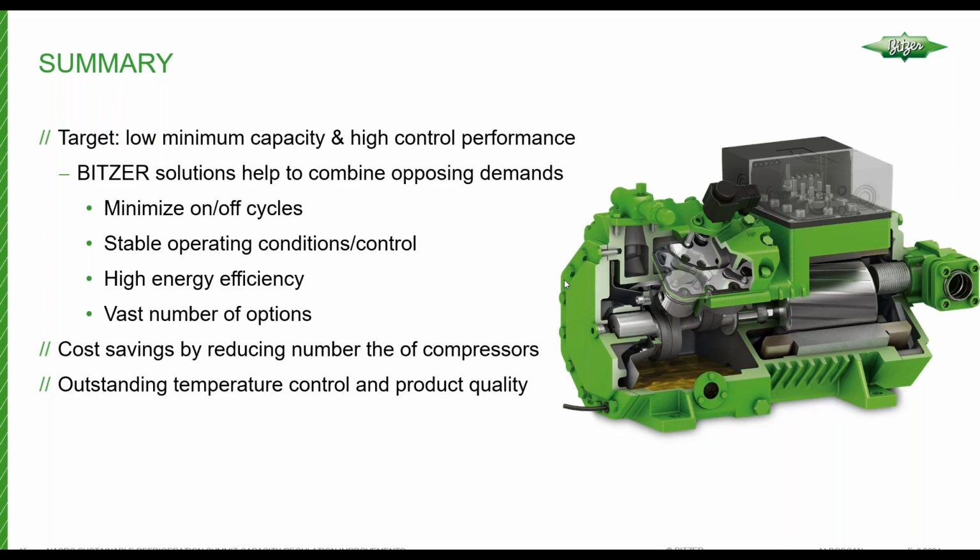It's not to replace the VFD. It can, but the intention is not that. It's to enhance the ability of a rack designer to use more tools to finally provide a very high efficiency, well-controlled system at full load and at part load. And with the Veristep, we feel that the BITZER option really solidifies the ability to do this with many, many different applications and operating ranges and capacity ranges.